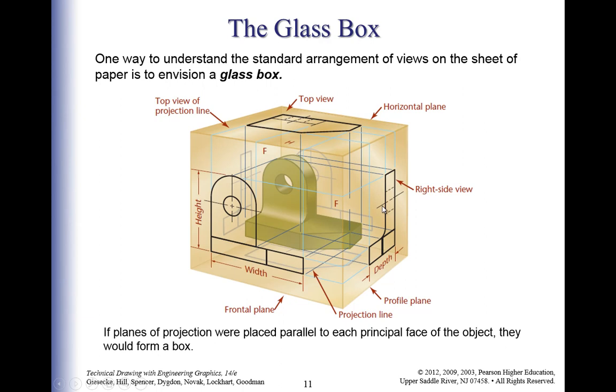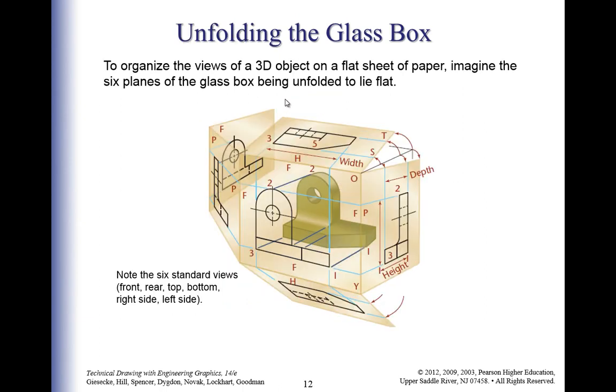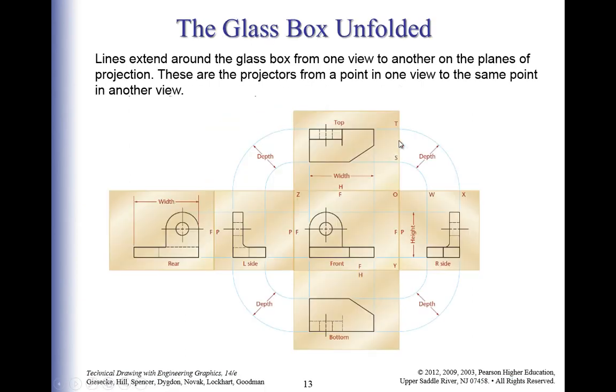Now to get this right side view, this is hinged right here, and then the little handle would be here and you pull it out. This line is hinged for a top view. We just grab the little handle and we pull it straight up and have a flat pattern. So that's how that actually works. And you see it right here as we unfold. This is the folding planes, remember that, and then here it comes open and it would look like this. Now this is our folding plane.